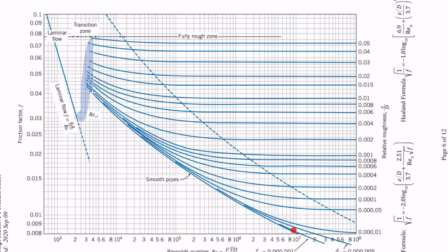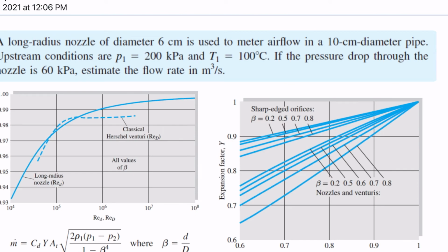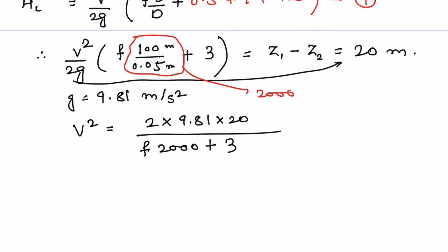We'll just assume the pipe to be smooth, but we need the Reynolds number to calculate the friction factor here. Because the velocity is unknown and the Reynolds number is unknown, we need to iterate by starting with an initial guess and iterate to converge to an exact solution.